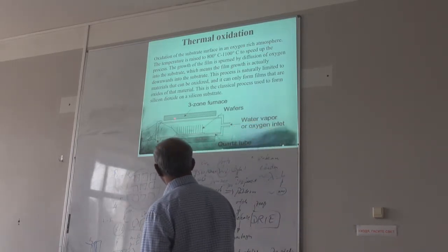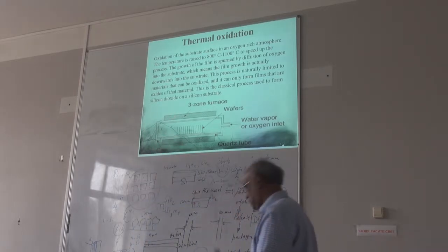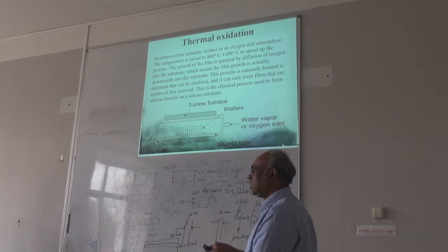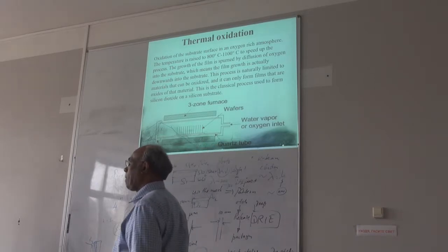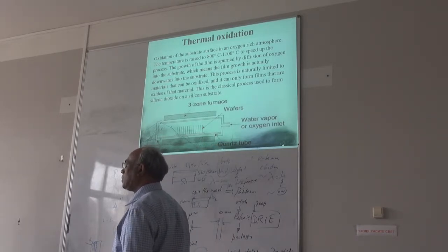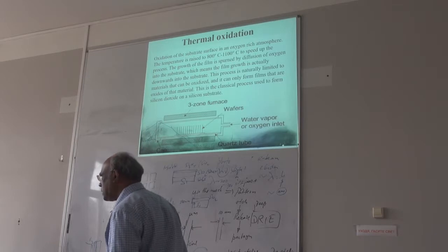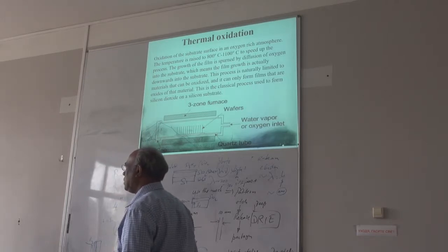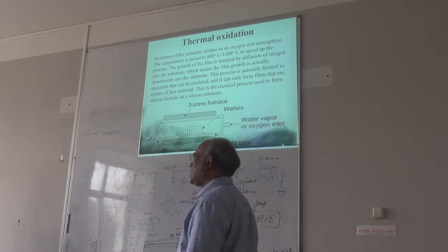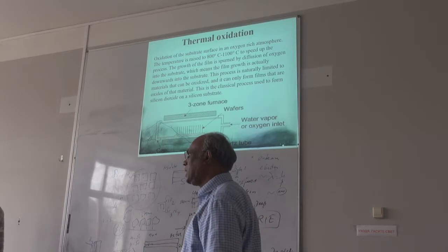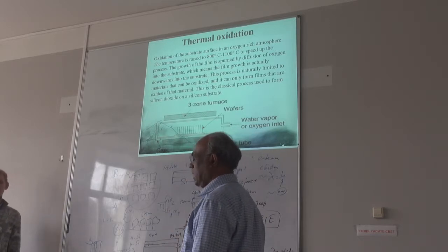So here you have silicon wafers just sitting like this, several wafers, and you pass the gas. Defects of growth: in this case there will be more defects inside the wafer, because the diffusion process is happening. Some defects go from the middle of the wafer to the surface, and you have some silicon vacancies and oxygen vacancies.